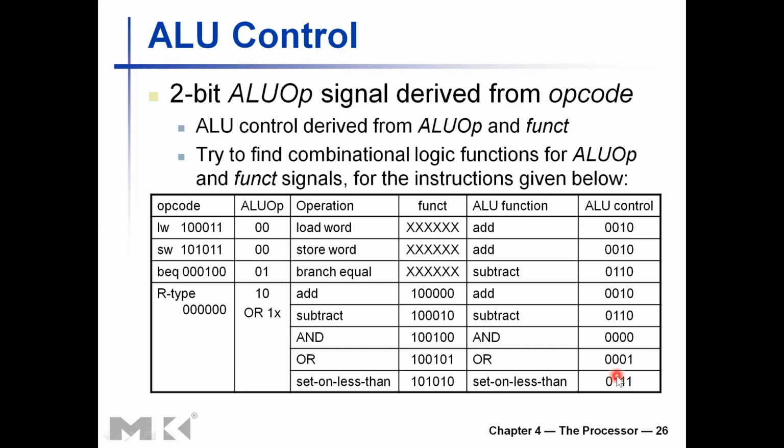Some control signals should be generated quicker than the ALU control signal, such as what to do with an immediate operand, whether you need to shift it, and whether the input to the ALU should come from a register file operand or an immediate operand.